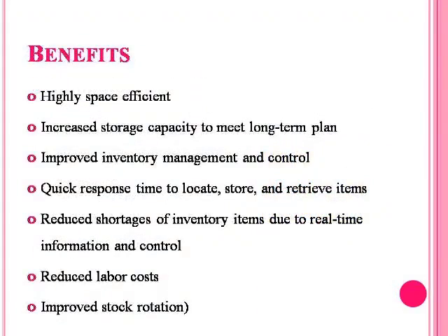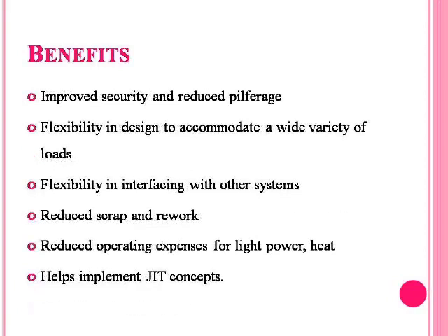The benefits of automated storage and retrieval systems include high space efficiency, increased storage capacity to meet long-term plans, improved inventory management and control, quick response time to locate storage and retrieval items, reduced storage of inventory items due to real-time control, reduced labor costs, and improved stock rotation. Also improved security and reduced pilferage, flexibility in design to accommodate a wide variety of loads, flexibility in interfacing with other systems, reduced scrap and rework, reduced operating expenses for light, power, heat, etc., and it helps implementation of just-in-time concepts.